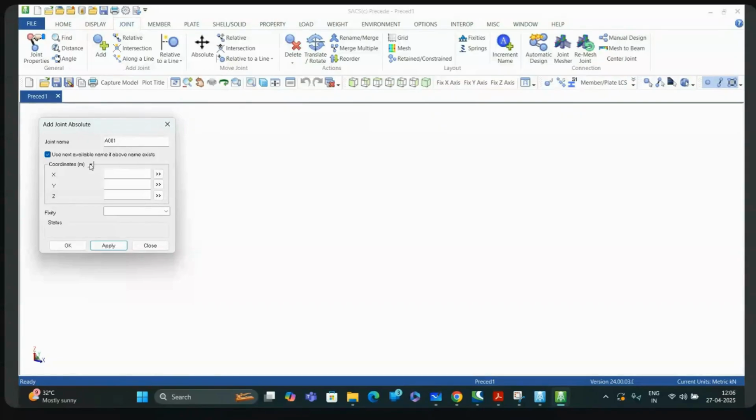Now the coordinate, it's very important. You should be very careful here. I told you, we set this as meter. It's a default. Now, if you are designing small structures, the coordinates you get may be in mm. It can be in centimeters. At that time, you don't do the painful thing of mentally converting it to meter or centimeter. You come here, select whichever unit you want, and give the coordinates.